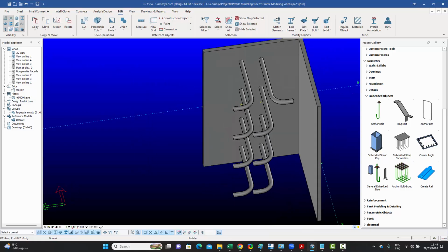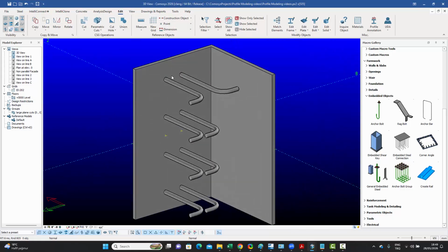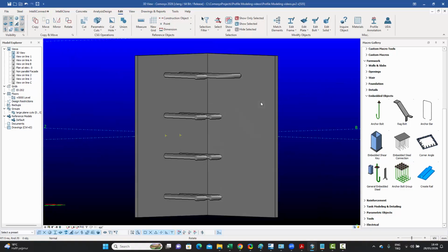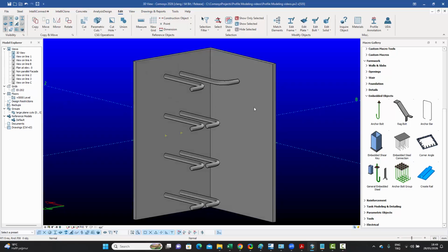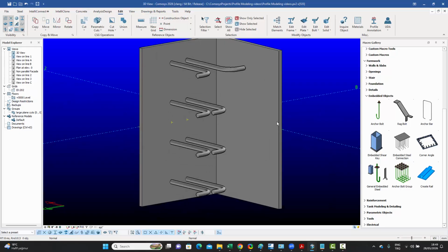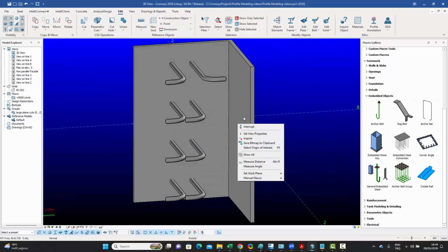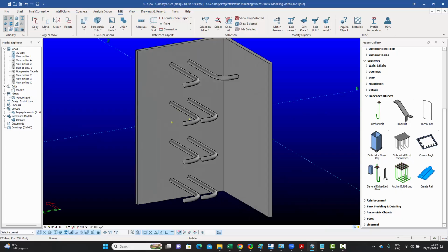And now that we have these bars coming out of the folded plate from that side, we can do the same. I don't have to repeat it, but we want them staggered. So we once again create these 2 points, 95, 50, but this time we'll move them to the middle of this line, and instead of 4 copies, we'll have 3 copies, and we will be able to create those rebars as well.